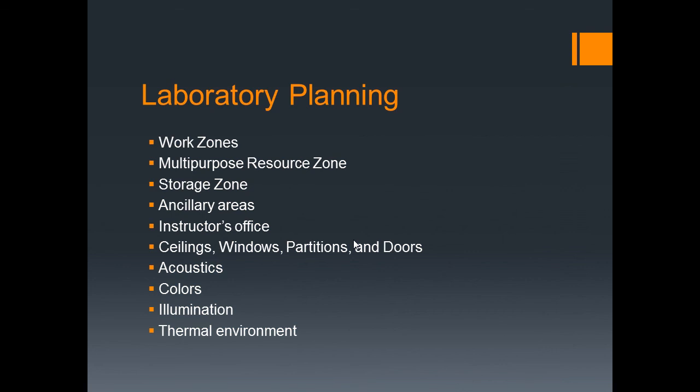If that light's blinking at 60 times per second and that blade is also getting turned at 60 cycles per second, there can be a situation where it looks like that blade is standing still if you can't hear the motor running. And I have heard horror stories of students and teachers getting their hands cut off because they thought the blade was still, but yet it was turning because of the strobe effect.